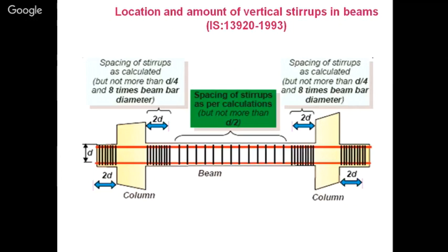This is the reason, because most of the earthquake force is being followed, or the behavior is like that, the beam column joint is having the maximum earthquake force. Most of the displacement is at that point. So we need to confine this part very much, whether it is beam column joint, whether it is column to column in between, or whether it is beam to beam in between.